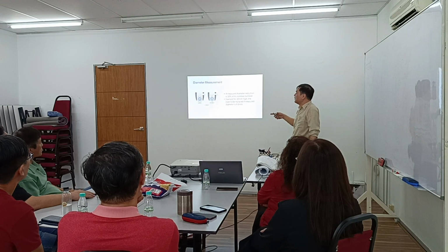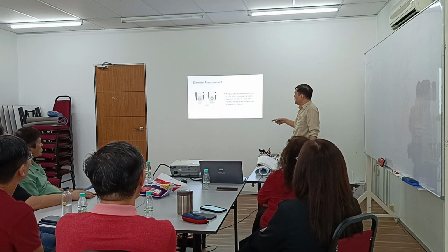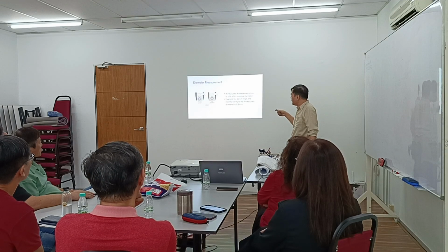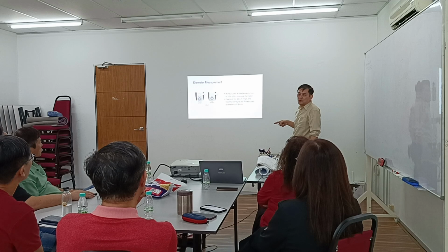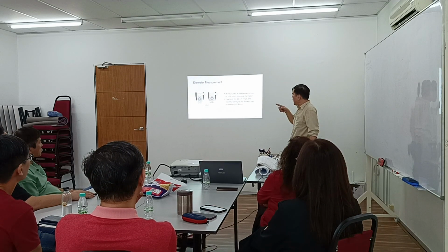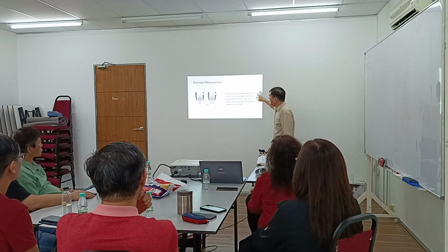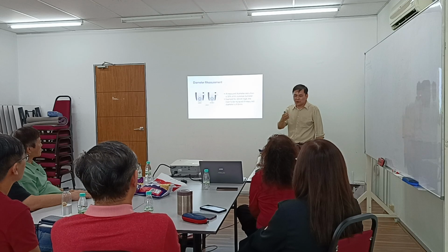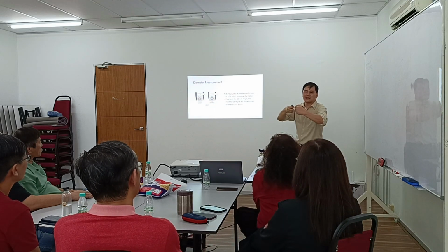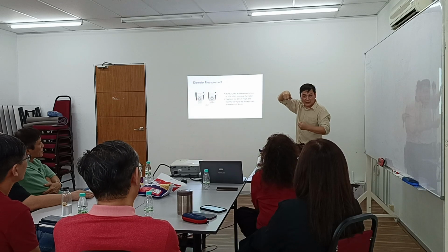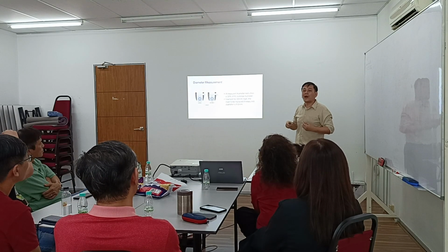So this is the diameter measurement. If the measured diameter reduction is 10% of its nominal diameter, we also have to replace. Okay, but if we argue, less than 10%, and I can check the tensile strength with the tool, and the tensile strength is still okay, why do I want to change?